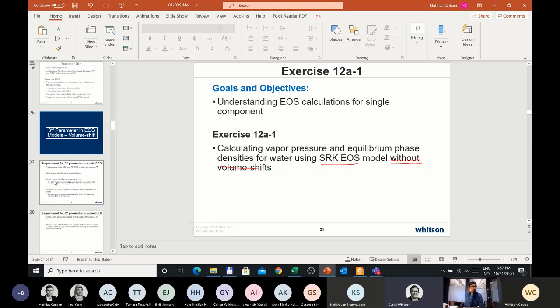When you get to high enough pressures like 700, 800, 900 bar, neither of the equations are going to give you compressibilities. Well, even at 600 bar, the compressibility of single phase gas or single phase liquid will not be right. For the same reason it's not right for water.